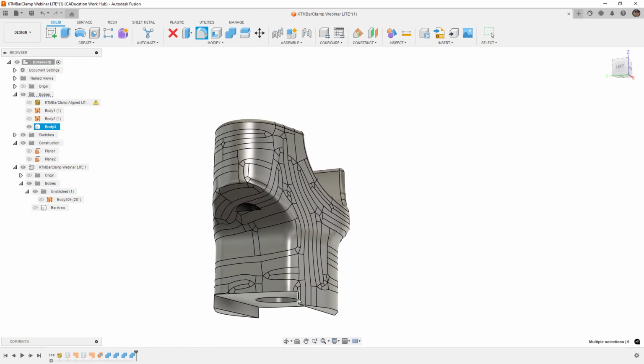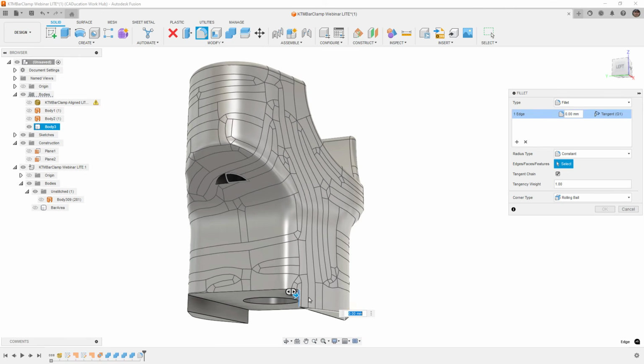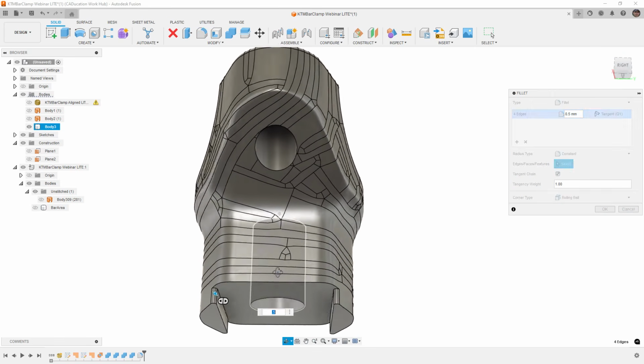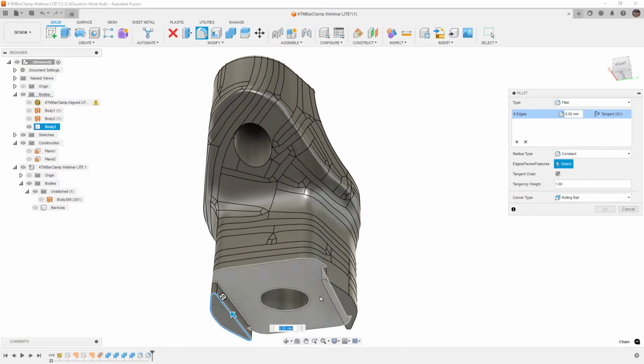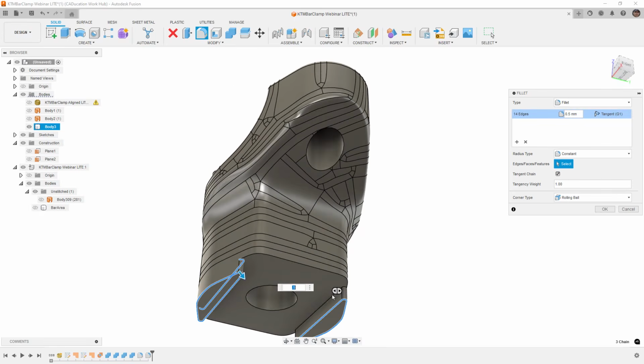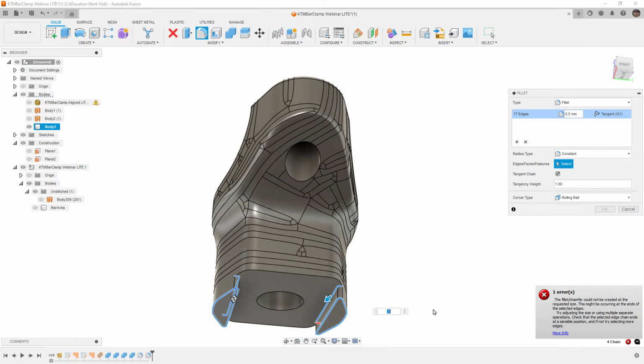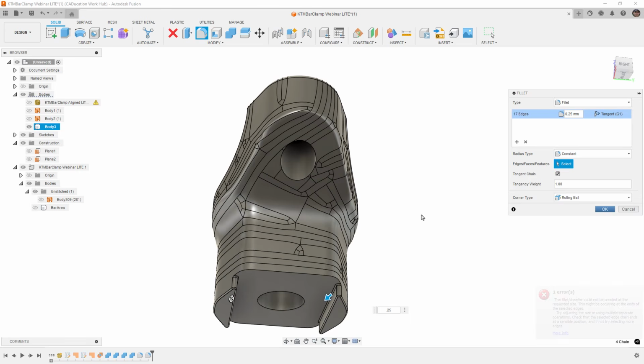And then hopefully we can add a fillet to here, probably a bit smaller. Hold down Control, and we'll add it there as well. And then the last thing is these had a very tiny fillet on them. And if you want to, you can add one in the corner there. It wasn't really a fillet there, but it wasn't exactly a square corner. Looks like there's some problems around the corner, so make it a little bit smaller and say OK.